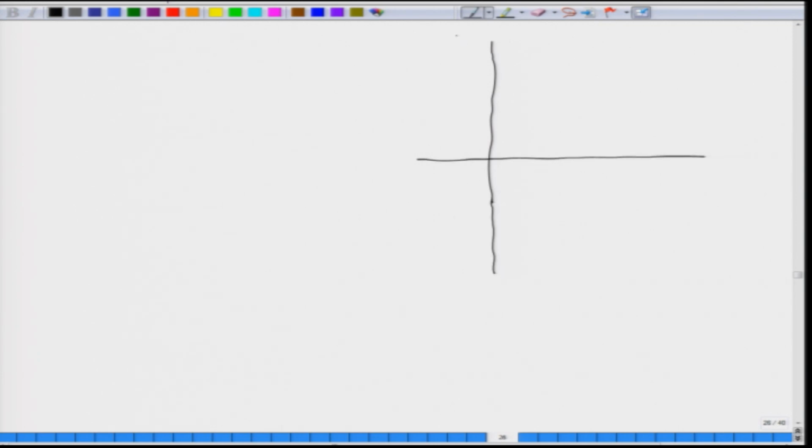So, we have the speed on the y axis and the torque on the x axis, with the origin in this case, and we have two fields. One is a forward field. So, we have a forward positive sequence torque here, which goes like this, and the synchronous speed here is plus omega ms. Then we have the reverse direction, where the speed in the negative direction is minus omega ms, that is the negative synchronous speed.